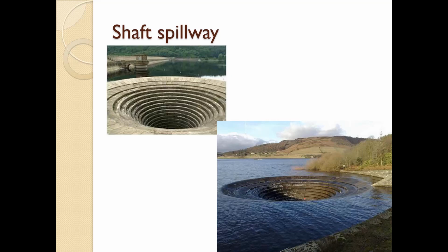For small heights the shafts may be constructed entirely of metal, concrete or clay tiles, but for larger heights reinforced cement concrete may be used. For smaller heights no special inlet design is necessary, but for large projects the flared inlet called morning glory is often used. The horizontal tunnel or conduit may be taken either through the body of the dam, as may be done in the case of concrete dams, or below the foundation in case of earthen dams.